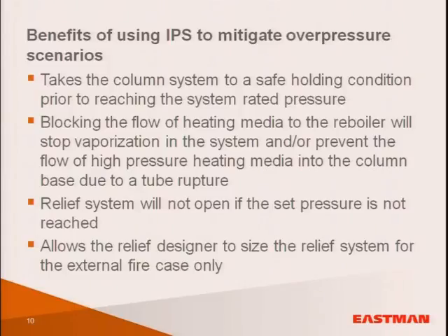The relief system won't open if the set pressure is not reached, and that limits the impact of the scenario because you don't lose containment through the relief system. And you don't have to size an effluent handling system for the release through the relief system for that particular event. And ultimately, it could allow the relief designer to size the relief system for external fire case only. You cannot use your instrumented protective system to mitigate the external fire scenario because you can't count on that equipment surviving the impact of the external fire.